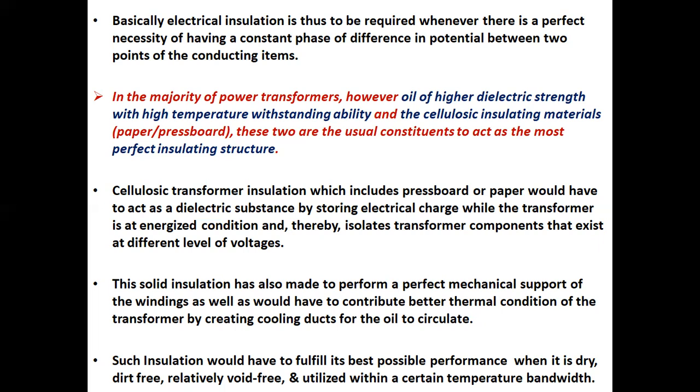This solid insulation is also made to perform as a mechanical support of the windings, and contributes to the thermal condition of the transformer by creating cooling ducts for the oil to circulate. Such insulation performs best when it is dry, dirt-free, relatively void-free, and utilized within a certain temperature bandwidth.